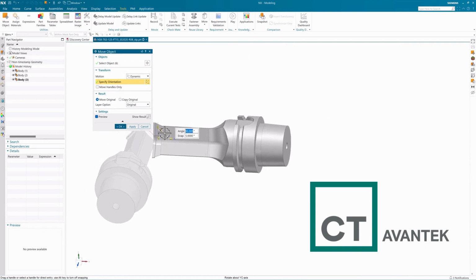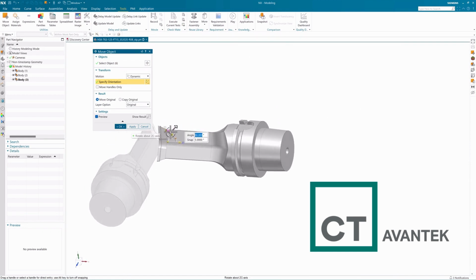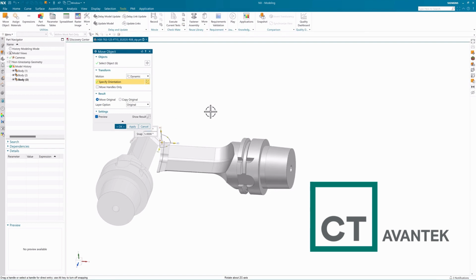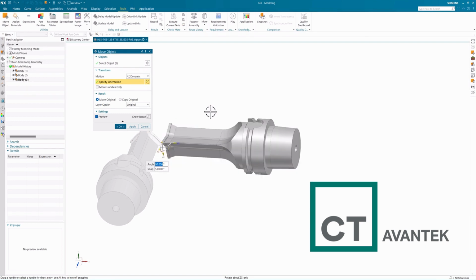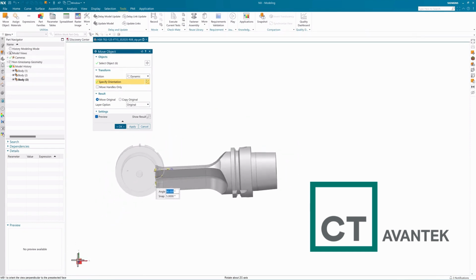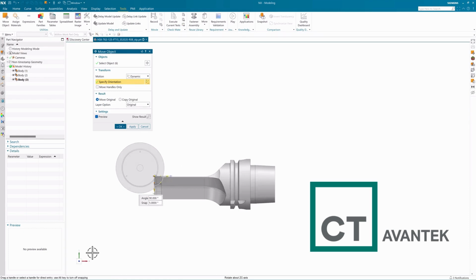The second rotation in this case to take care of is the position of the index notch. The index notch is important for reference when it comes to the initial tool position. Let's start by rotating the tool 90 degrees around the Z-axis to see where it ends up. We can now see that an additional rotation of 90 degrees is necessary to correctly position the tool, with the index notch pointing down and in plus Z-axis direction in ACS.